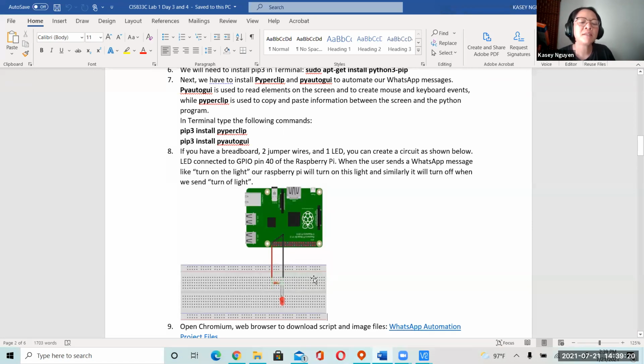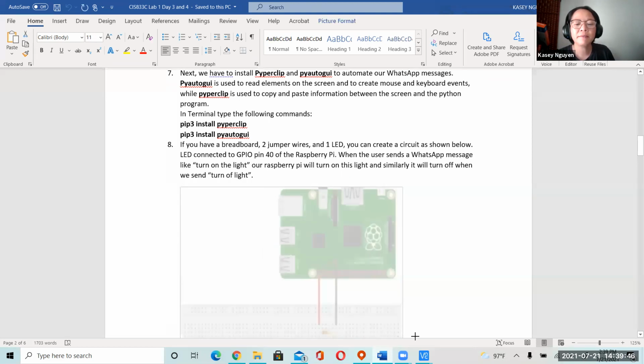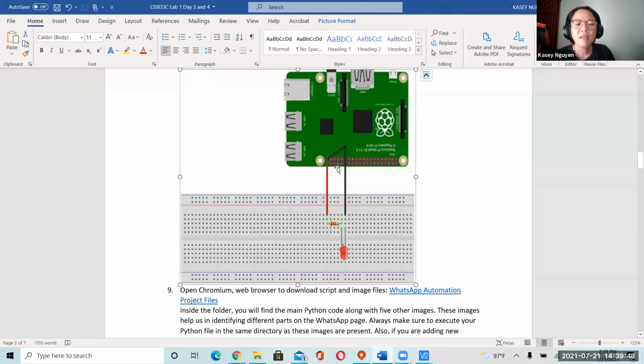You can adapt sensors. And the breadboard, think of it as a way for us to connect the electrical components where it would send signals. When you use the breadboard, you want to make sure that your wires line up with the electrical components' connections. For example, if you look at this picture, I'm going to pull it bigger. This is a ground wire and it needs to line up with the short leg of the LED.